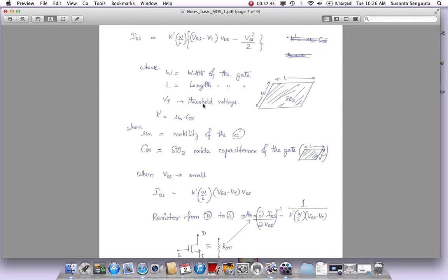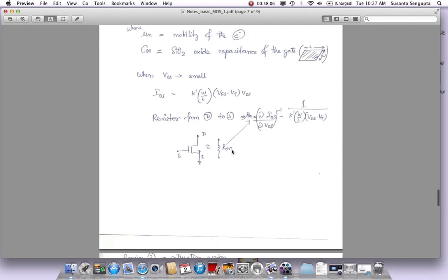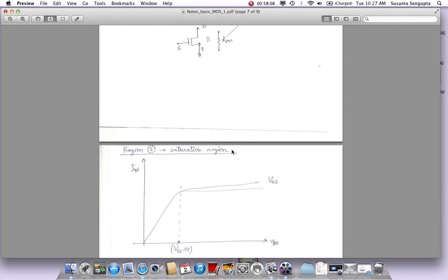And once you do a design on paper, you put it in a simulator, and from there you fine tune it. So you don't go to the simulator directly, with all these CAD tools you have, Spice, Cadence tools. You don't put a design there and start playing with arbitrary values. No, you should always use these simple equations to do a first order, pencil and paper design, using simple hand calculations. And once you have it, then you go to the simulator for fine tuning.